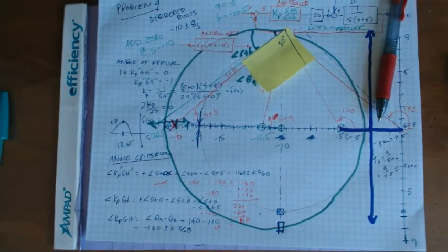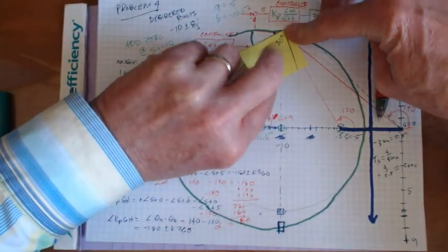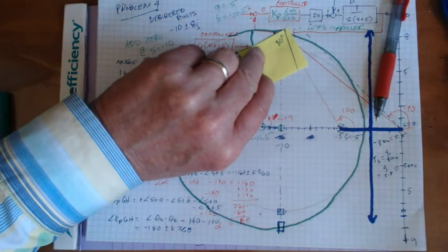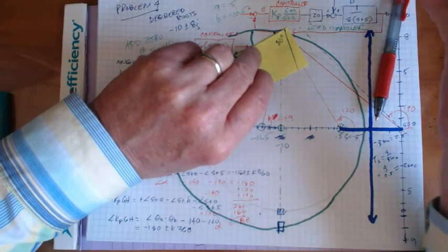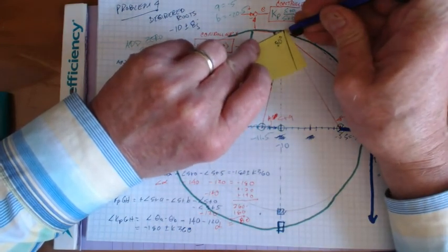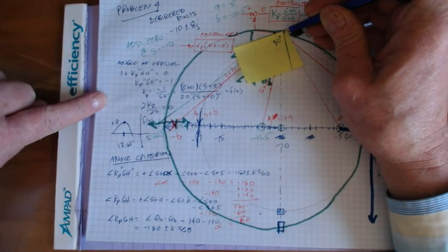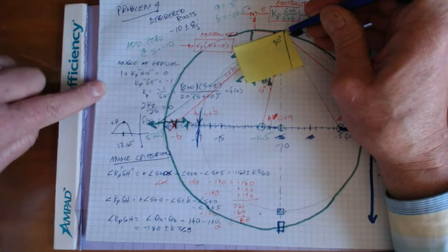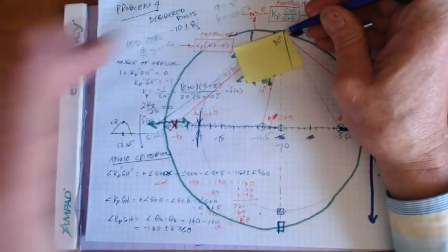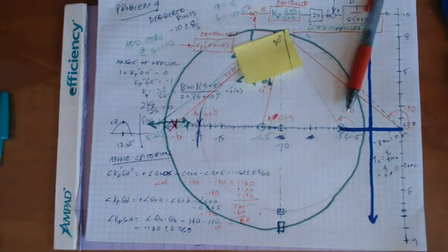Perfect. And we're done. We're going to want to simulate all this as well, right? And I'm also going to tell you, it's not a bad thing to try and cancel poles and zeros. We'll talk more about this. In general, you don't want to. In general, what you want is to push this pole out as far as you can get it. If you can get it 3 or 4 times farther out than your dominant root locations, you're good. And then wherever this one goes, you just have to live with that. Okay, so you can try those things.